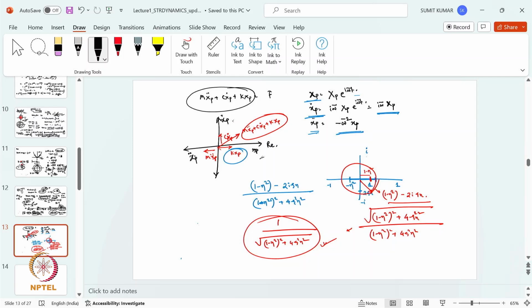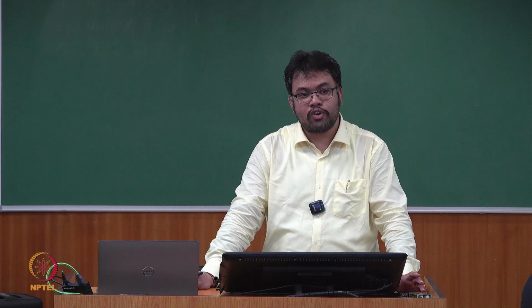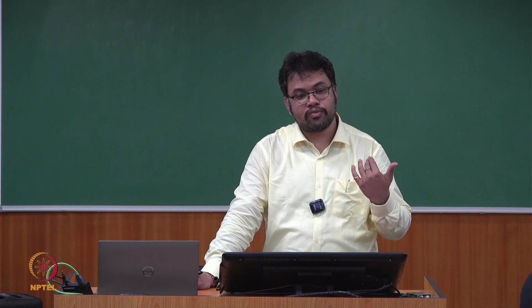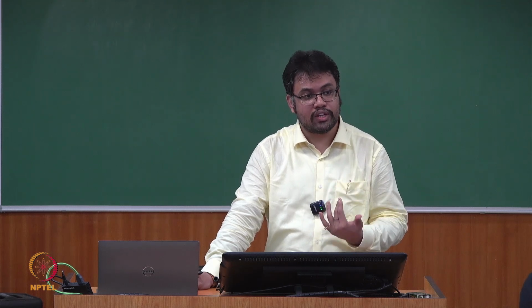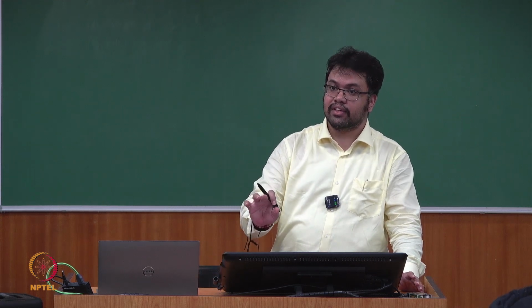We see three vectors: one corresponding to the inertial force, another to the damping force, and another to the elastic restoring force, and we can also locate their combined vector. If we calculate the modulus of that, it gives the particular response. That gives the amplitude, how much it is reducing, and whatever the angle is, it tells that the response will be shifted by that much phase angle.